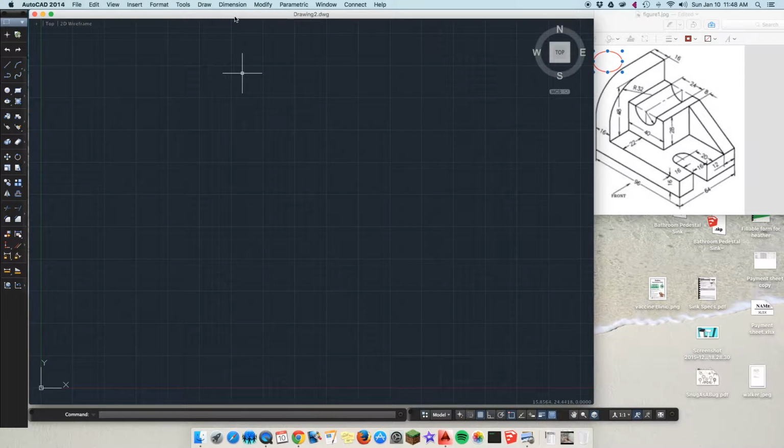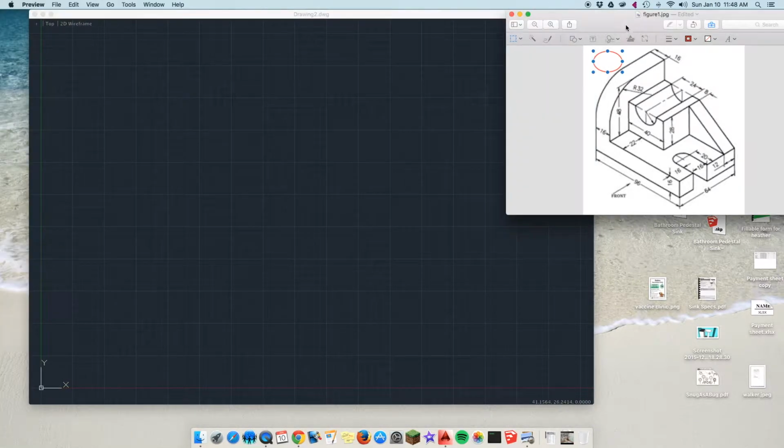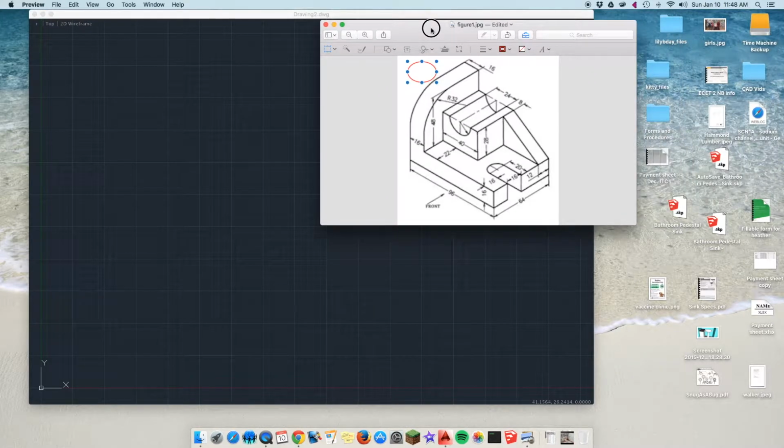Okay, so today we're going to talk about a tool that has been right in front of us the whole time and we haven't really used it. But down here where the X and the Y come together, we know that's 0, 0 down there, but it's called the Universal Coordinate System, or UCS for short, and it will allow us to kind of draw on different surfaces.